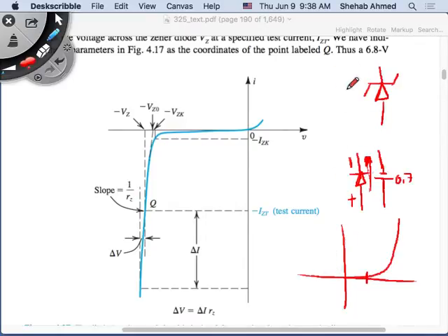In the reverse mode, the model of the Zener diode will look like this, right? Where this flat symbol is, it's opposite the diode model. Why is that? Because I'm actually in the reverse mode here. So only when I put a reverse voltage, in the same direction as this negative Zener voltage, will the Zener conduct. Okay?